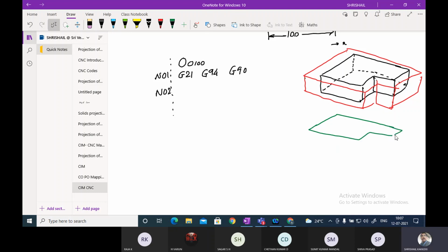Try to understand this. One mm depth milling is done. Still, this raw material will be like this. You understood? It has started from here. Yes, sir. It has completed this much. Again, it will come back. Then again, the next step, what happens? Again, it will take under 1 mm depth. It will complete this. So this particular material will be removed in terms of 1 mm depth.